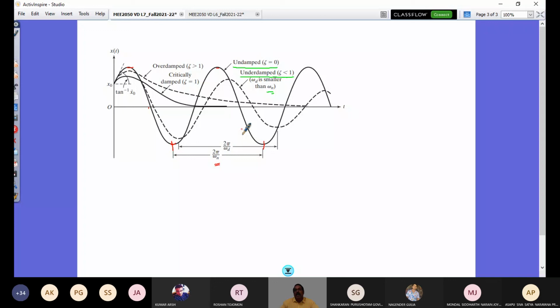So delta would be, if I have m cycles measured, the ratio of the first amplitude to the mth amplitude, the logarithmic ratio, divided by m. So this is 1 by m ln of the first amplitude, not the successive amplitude. After m cycles, whatever amplitude we have, that is possible to get in the experiment. Then your natural logarithmic decrement would be defined in this case. So this is how you define what is called a logarithmic decrement.